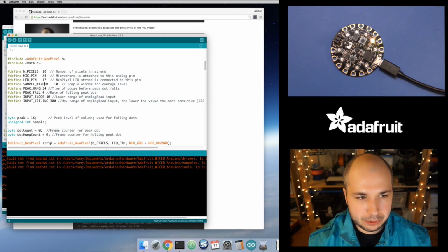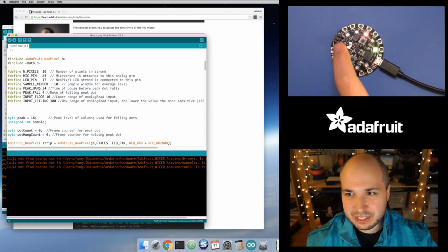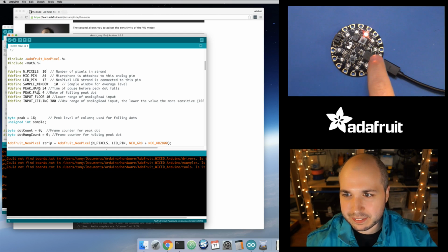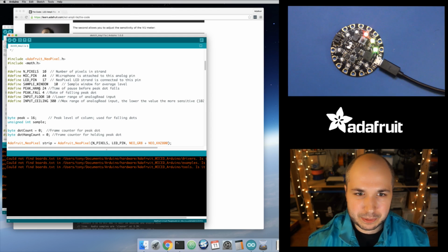And I'll walk through the code, and you'll see how this stuff works and why some of this matters. There's a period of time where it'll take a few samples, and then it's going to look for the minimum and the maximum value within those samples. And then there's a falloff period where you can see, as I talk, if I talk really loud, then the pixel animates falling back down. That's because it's taking your max value, and even as your sound stops, it'll animate that falling back down to 0. So it's a neat little animation to show you here was the max value that you saw for the sound volume.